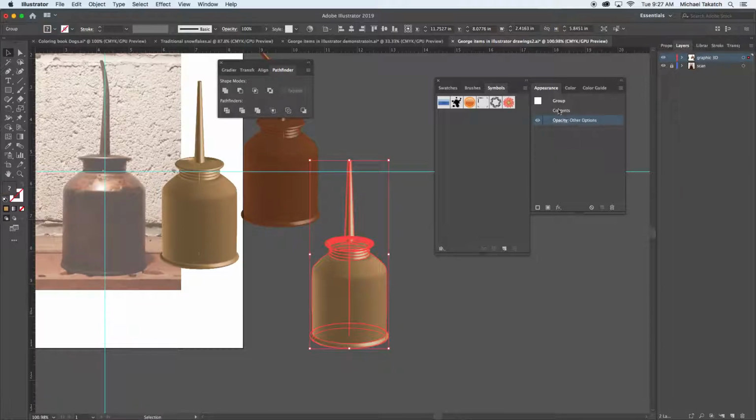You'll see it disappears over here. And you can change this. So rather than try to bend this, there's a tool that looks like a thumbtack. When you click on it, you can set this part and twist this, so it lets you turn some things that are three-dimensional that you couldn't have done in the model. The only trouble is you can't go back to edit this as a three-dimensional model. As this goes over, you can see it has these lines that show the different shading that's broken apart. So everything is now a broken up shape, so a little trickier to edit.